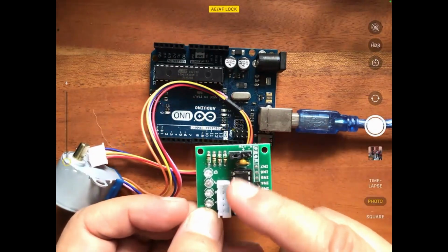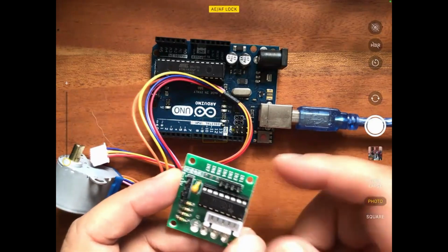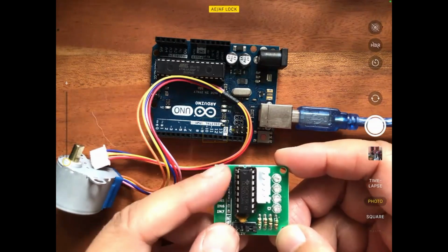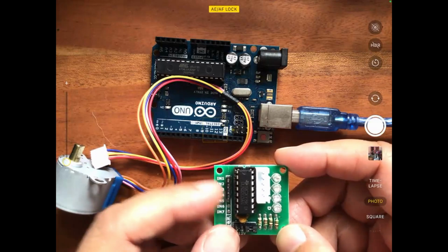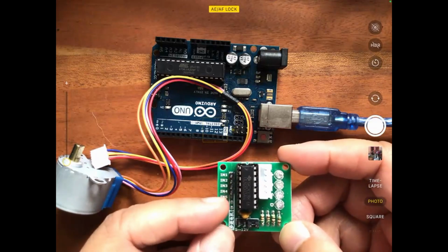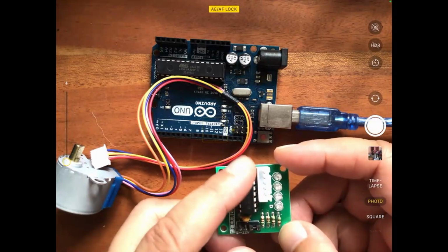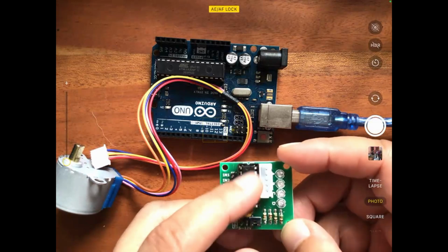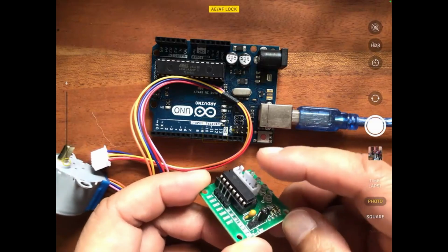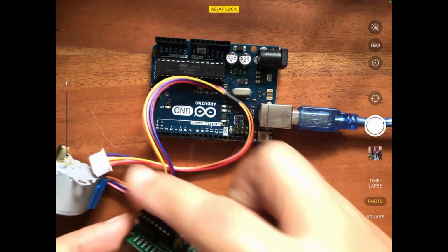This is a bunch of resistors that will convert the digital input that will get in here. Di ba nga, nakita nyo dun sa table kanina, you need just to turn on and off some of the coils. But there should be an increase in power, and that increase in power, or current, will be implemented by this set of transistors here. And this is where you will attach this cable here to the motor.